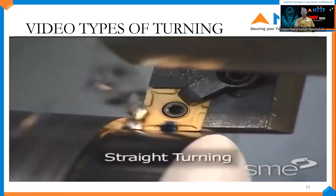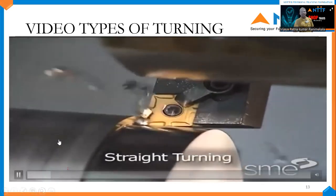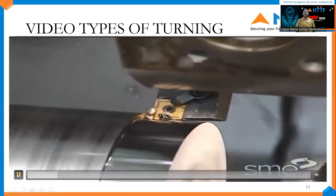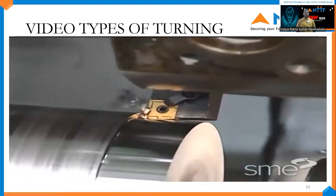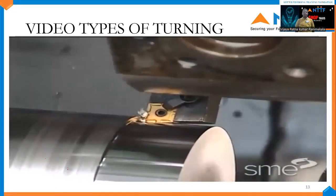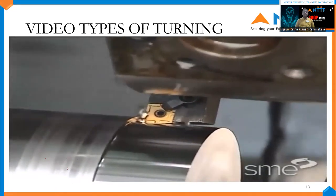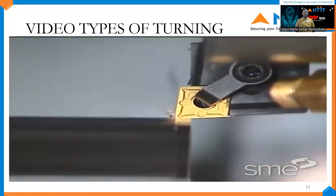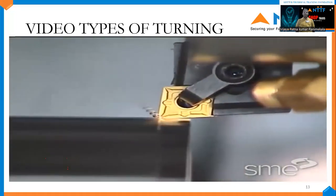Here in straight turning, the tool is fed parallel to the axis of the work. Here this is the cutting tool. This is a cylindrical workpiece, turned to reduce its diameter so that the final diameter is the same at each end. Removing a significant amount of material in one pass is called rough turning. The final lighter cut that creates a smooth surface finish is called finish turning.